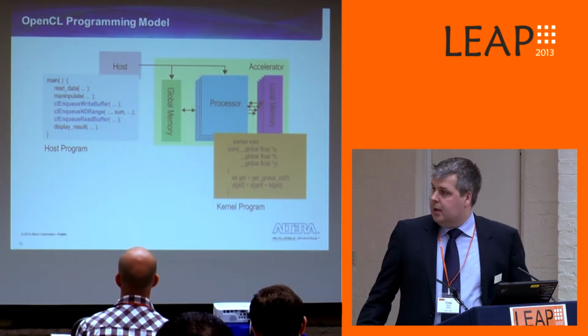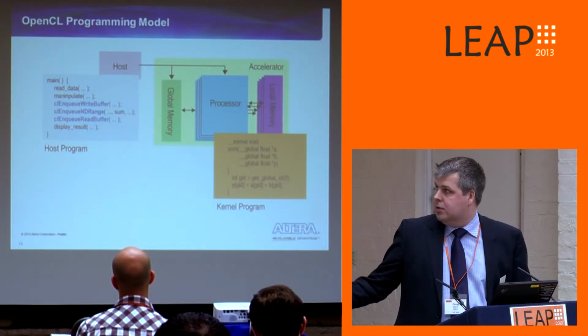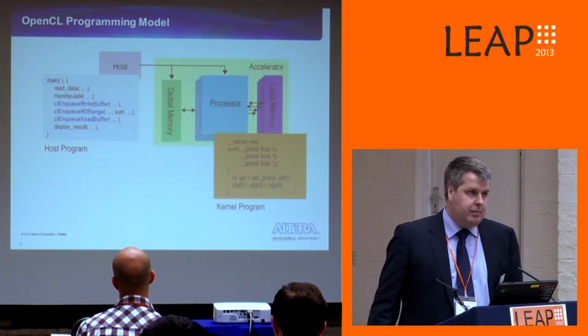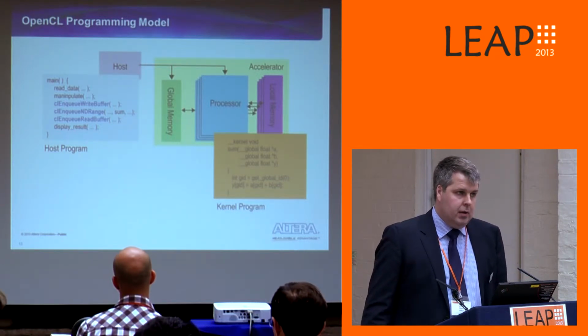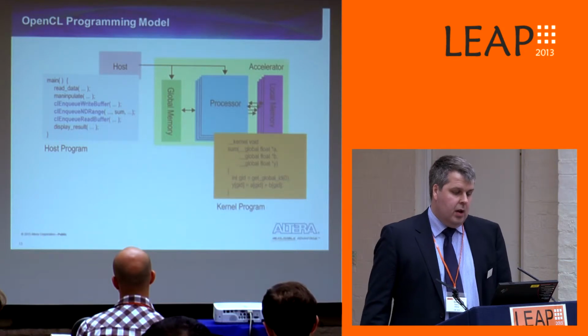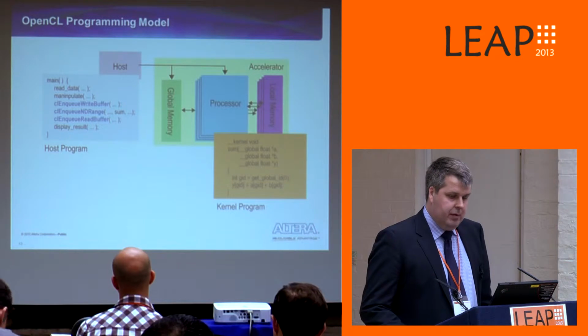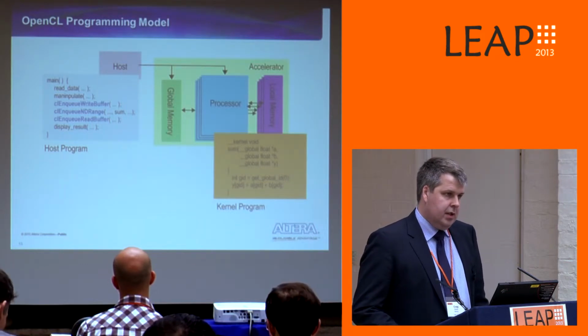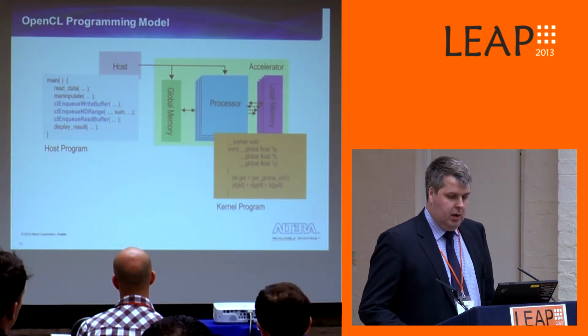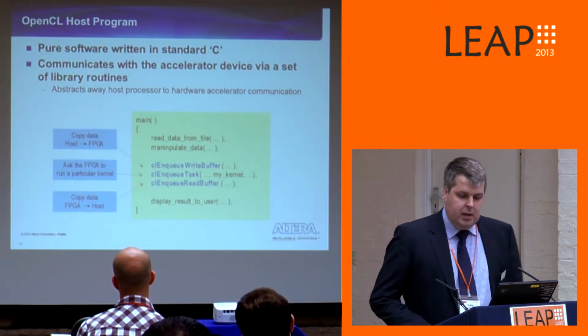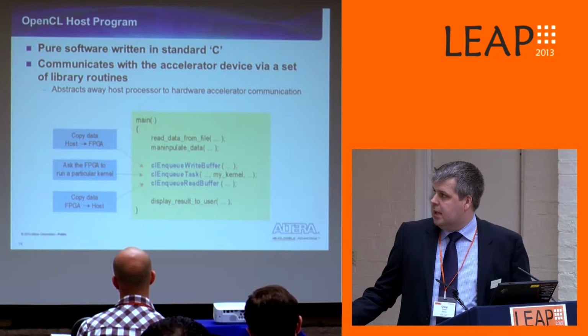We're calling the standard OpenCL calls, writing data from the host via an interface to the FPGA, running the kernels in the FPGA and reading the results back into the host, and then building inside the FPGA all the logic you need to connect to global memory, produce your kernel accelerations and local memory on the FPGA. The host itself is essentially standard C code.